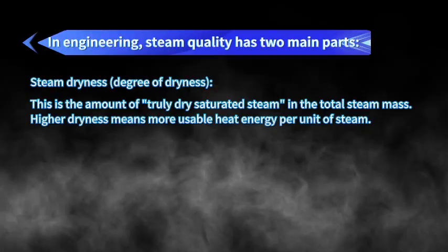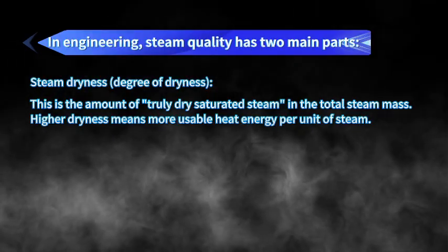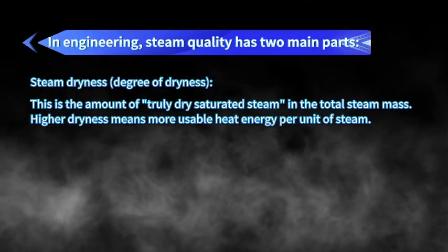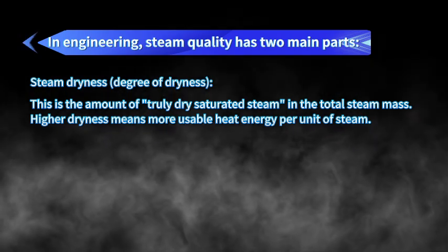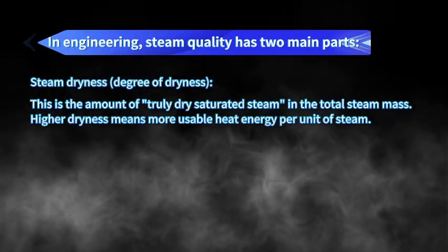If steam contains many water droplets, it may seem fine. The pressure and flow might look good, but the useful energy for heat transfer is lower. This can also cause erosion and water hammer.